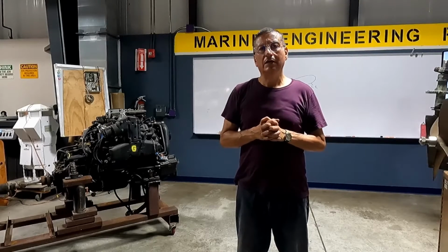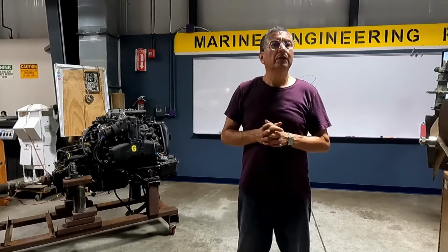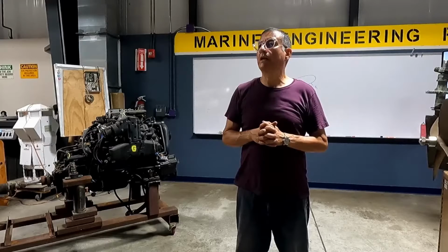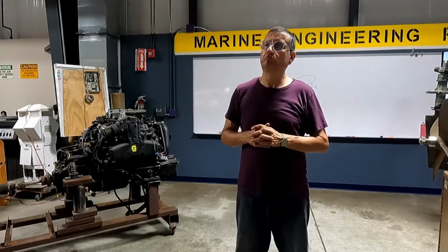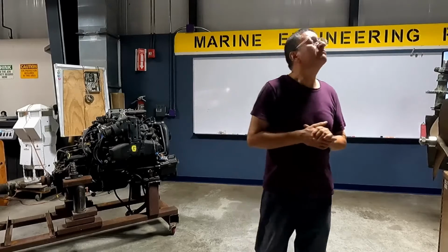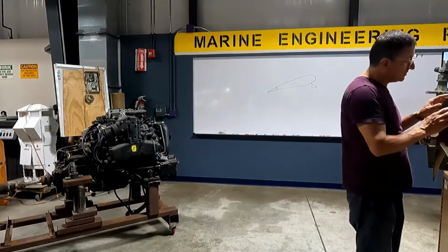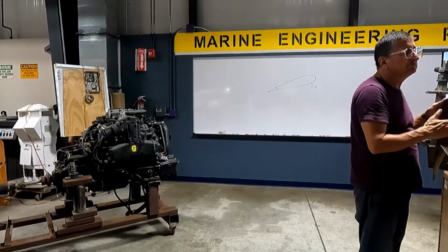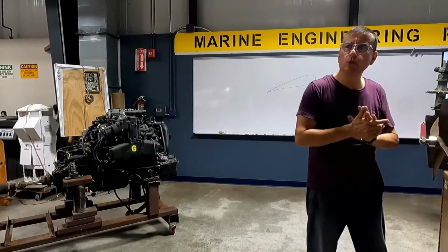If you have a crack on the blade exactly on the hub, it's garbage. I don't recommend repairing the propeller over there. I don't recommend welding in that area, right at the base of the blade. I recommend repairing the blade if the blade is bent, you can. But here, no. Finito. New propeller.